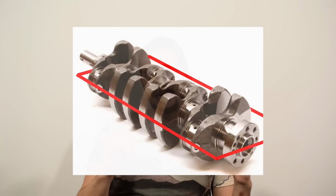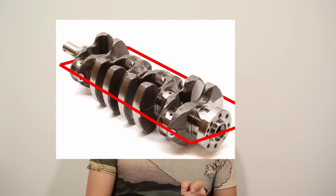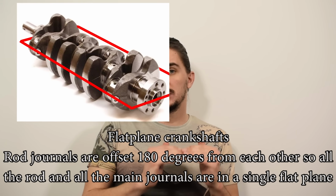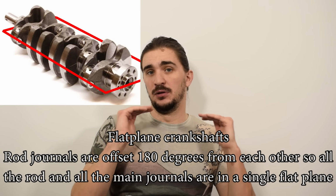Now, the comparison between flat-plane and cross-plane crankshafts deserves an entire video on its own, so here we're going to just briefly summarize the two types and look at the pros and cons of each type. Flat-plane crankshafts, as the name suggests, are in a single flat plane. The rod journals are offset 180 degrees from each other, which means that both the main journals and all the rod journals are in a single plane.